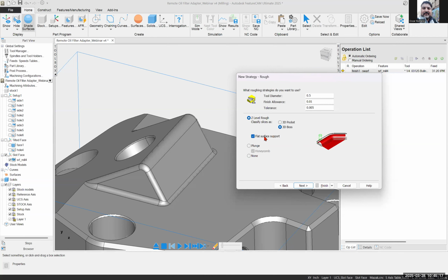So I'll take you through the rest of this. We're going to do a roughing. And the next one is the semi-roughing or semi-finish, depending on how you want to look at it. This would be applying a separate tool to get even closer to the finished dimension of the part before you actually finish. So this could be where you apply a parallel style finish, a semi-Z finish, or a finish in Z, right?